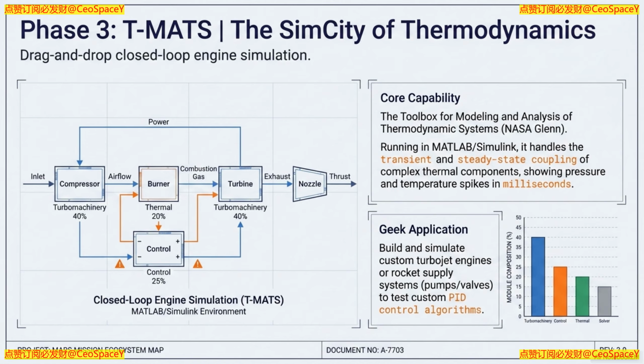Yeah, please do. So 6DOF means the simulation calculates movement along the 3 spatial axes: moving forward and backward, moving side to side, and moving up and down. That's 3. Okay. And then there's the rotation around those axes, right? Yeah. Pitching up and down, yawing left and right, and rolling. So that makes 6. Exactly.